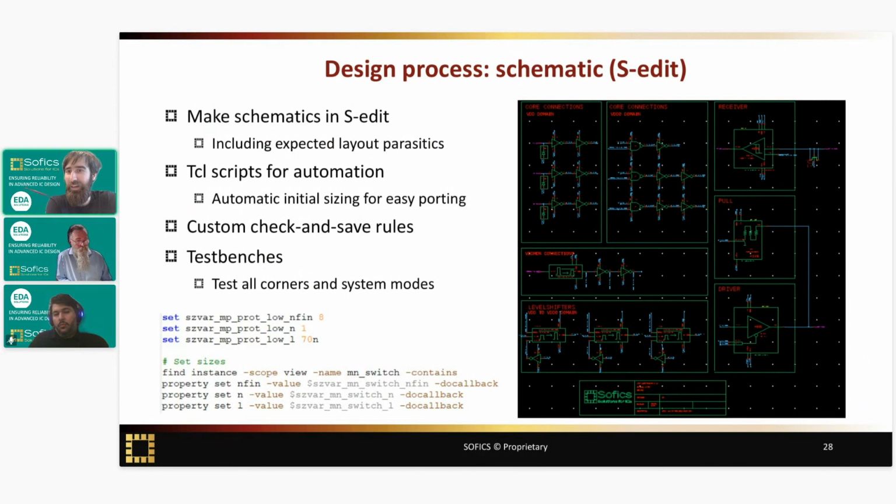Yes, absolutely. Running them before PEX. In order to run PEX, you will need some layout, which will mean you are way further down the design flow already. So including some layout parasitics that you expect very early on in the design process will help a lot. I'm mainly talking about well diodes that you expect. And there, just adding them is most often already sufficient, because if these diodes come into forward conduction, then they will already conduct significant current, even if they are quite small.